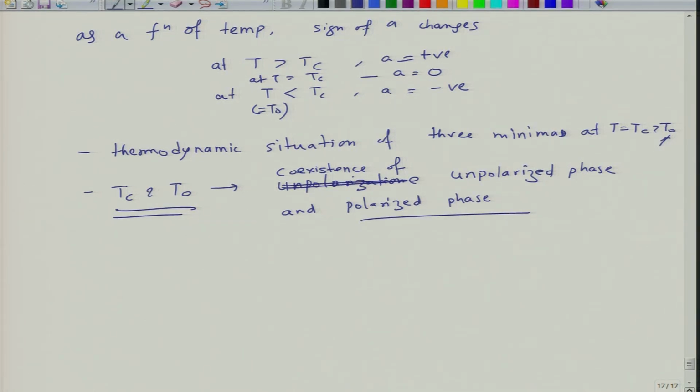When you transform liquid into a solid, right, all of the liquid does not convert into solid altogether, or all of the solid does not convert into liquid altogether. There is a range of temperature when liquid and solid coexist. You can explain this in the case of solidification on the basis of undercooling and the energy required to create a critical size nucleus and so on. Perhaps similar explanations can be given here, that to nucleate a stable polar phase you need to wait for some time, some undercooling is required.